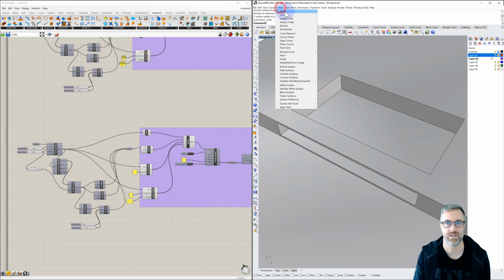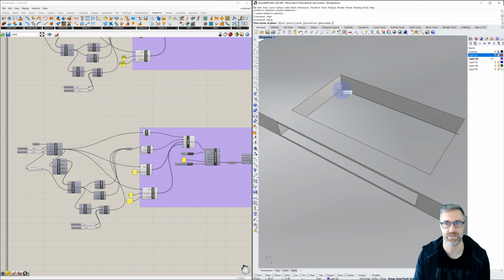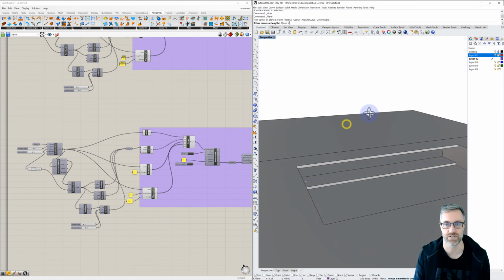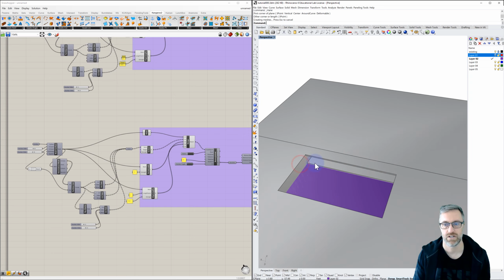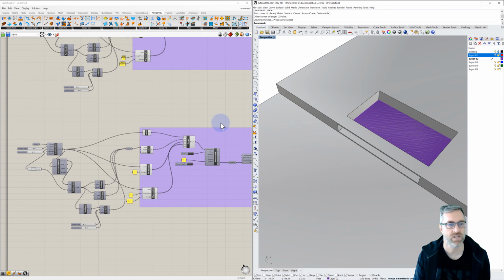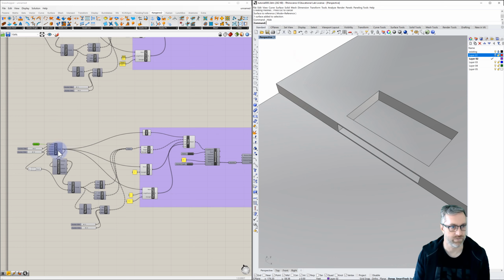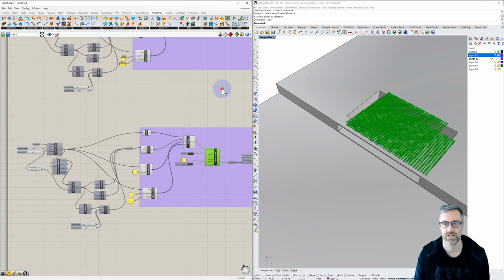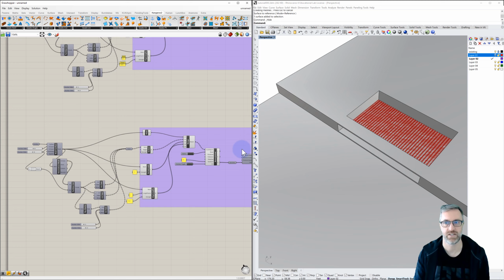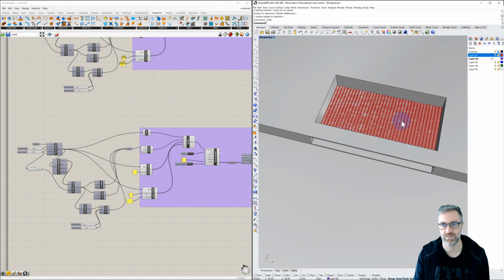So we'll start with a planar surface. I'm just going to fill the courtyard space with a planar surface. We can set our surface container with this one surface. So that's there. I can hide both. Hide it in Grasshopper and hide it within Rhino. And we have a mesh surface. Actually, let's turn on our solver. And we can even just reset it. So now we have our mesh flat on the ground.